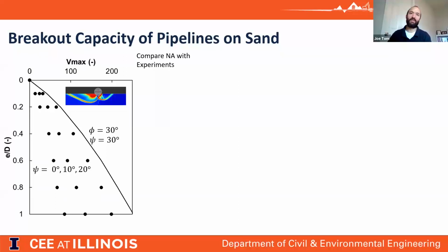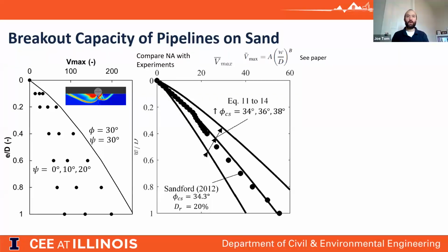It's interesting to then compare the elastoplastic FEA results for non-associated flow with some experiments. What we did in the paper is compare versus some experiments done by Richard Sanford at Oxford a few years ago, where he had a bed of sand with a certain friction angle and density. We can associate the density, using Bolton's relationships, to give us peak friction angle and peak dilation angle.